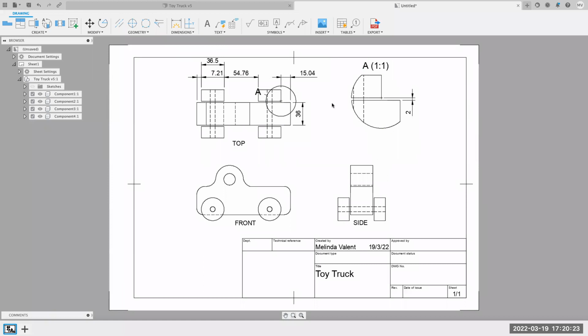And of course, because I didn't have that 3D view there, I had the space to do that. And that is important for orthogonal, that we provide as much detail as possible without getting too overcomplicated. So if I've put a dimension somewhere, like here, the 36 wide, if I put a dimension on this one that was also referencing the exact same thing, this is considered doubling up and over dimensioning.